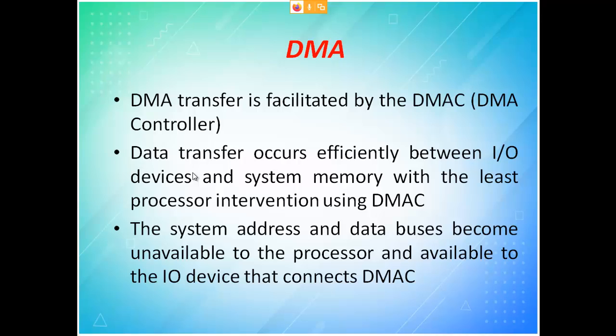So the processor will do some other task. Usually when you copy content from a CD to a pen drive, you are not sitting and watching what is being done. You will just go to Internet Explorer and do some other task, or go to some other Word file and sit and type. That is what we say here, and that is why the DMAC is required. You ask your pen drive to copy into your memory, and then you start doing some other work. That other work is done by your processor, and this copying work is done by the DMAC.